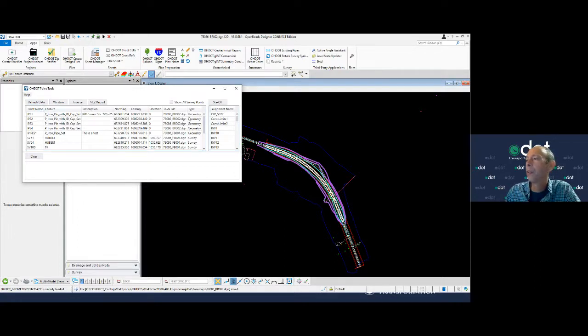As far as the features that they're showing here, these are for geometry points, it's just any geometry point. For survey points, it's a filtered list. So it's only the various control features or monument features, and that's kind of hard-coded by the app itself. If you want to see all the survey points, there's a button here, show all survey points, and that'll just read everything that's in the survey. So you may not want all the topographical type points, so you can turn those on or off.